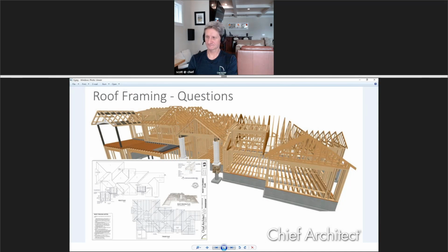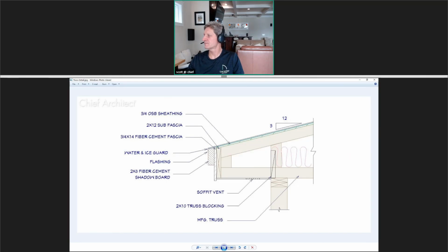Every truss plant we've ever worked with throughout Oregon, maybe they all use MiTek plates or something, but the measurement is to the bottom of roof sheathing or top of the top chord to top plate. And then they want us to go through the plan and identify that on every truss. Well, the truss profiles pop up nicely. There isn't any auto dimension or a way without doing CAD lines to throw a dimension on there to show them those heel heights everywhere. That would be a wonderful tool.